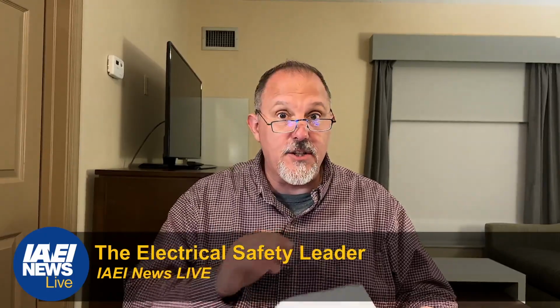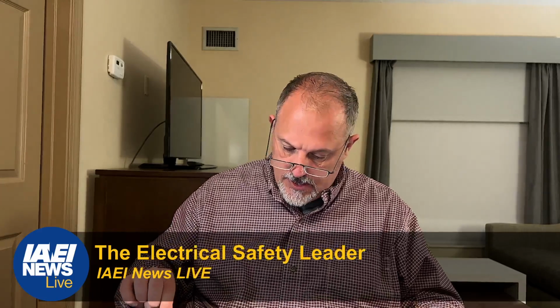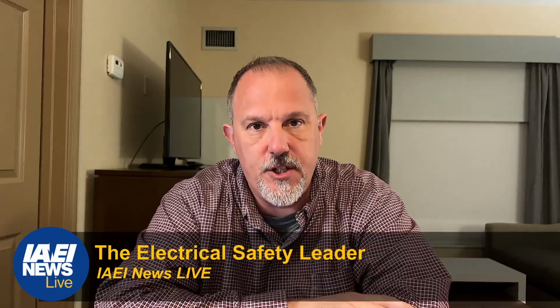I believe, oh, we got it in 680.58. This is in your Part 5, fountains. So we have special purpose required in Part 5 for fountains. Let's see if there's any other place. That's pretty much it. So 680, and then the other location is your grow facilities. So we see the introduction of a special purpose GFCI.